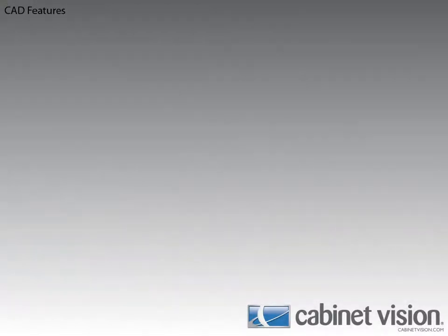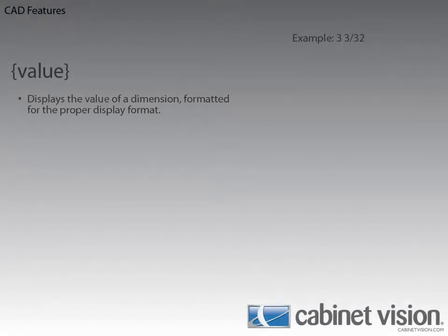Before we go any further, I want to talk about the formatting variables that we can use to create a format. You saw that the 3/32 option had the value variable in it. Each variable must be contained in curly brackets for Cabinet Vision to convert it to the proper number. So let's start off with the value variable. Now we're going to work on the assumption that Cabinet Vision is displaying dimensions using the imperial system. Also, we're going to be working with the example of 3 3/32 of an inch. Now the value variable will display the value of a dimension formatted for the proper display format. For our example, this means that the value variable will display 3 3/32.